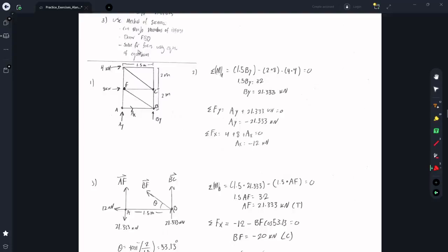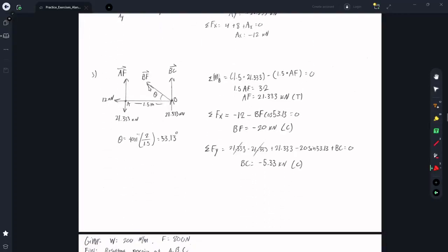So now we're going to apply the method of sections. We want these three forces, basically, which is convenient because we can just cut through all three members here and then draw the new cut truss. We can draw those cut members as forces. So we're going to model all of them. We're just going to assume them as all being tension forces. And then if we get a negative force, we'll just say that it's in compression. So here we have three unknowns.